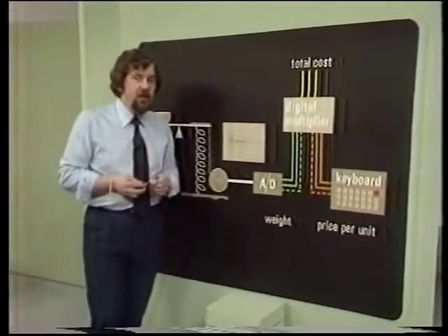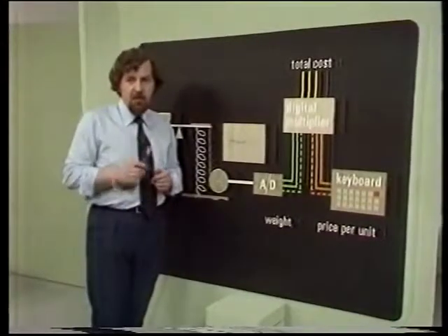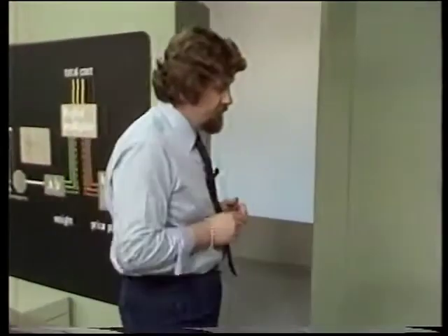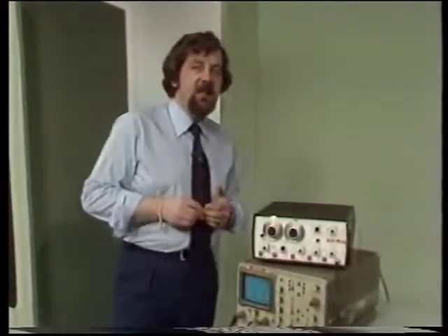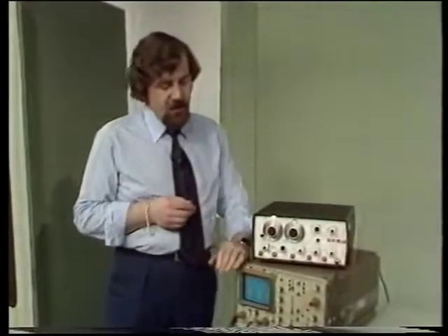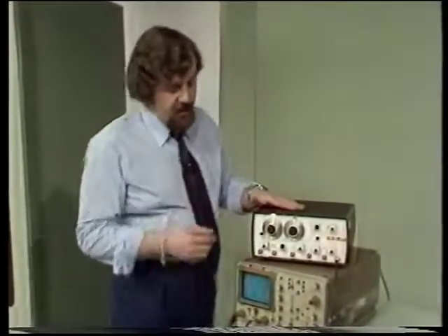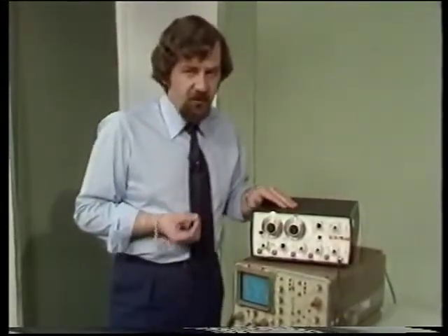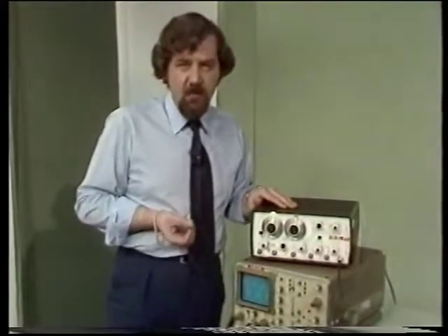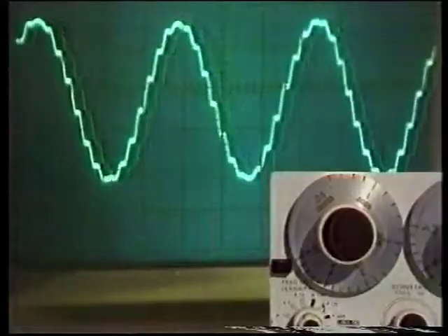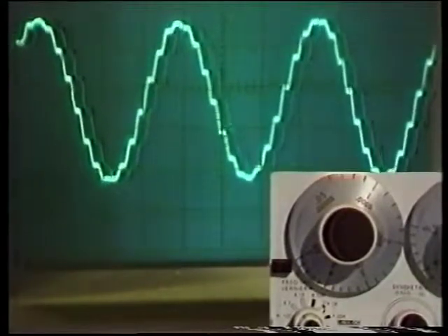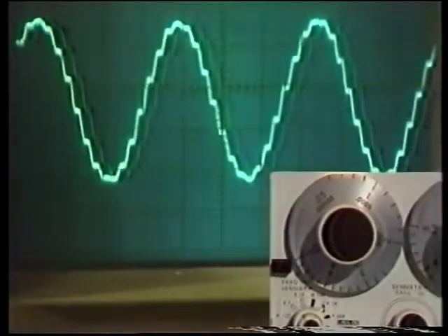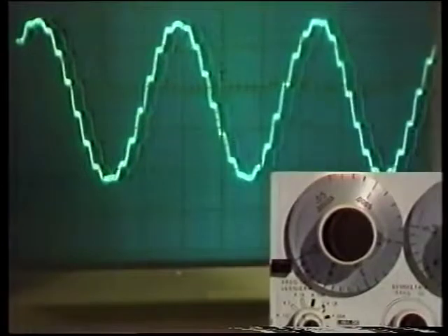But what about non-decaying AC signals? There are a few pitfalls, and I want to show you them. Let's examine a sine wave using this digital oscilloscope. The oscillator is providing the input, and the input is sampled at a constant rate, and the sample stored in a digital memory. I can display those samples on the screen, and if you look, you can see the samples. They're the little horizontal lines. And to make the display somewhat easier to view, they're joined up by straight lines.